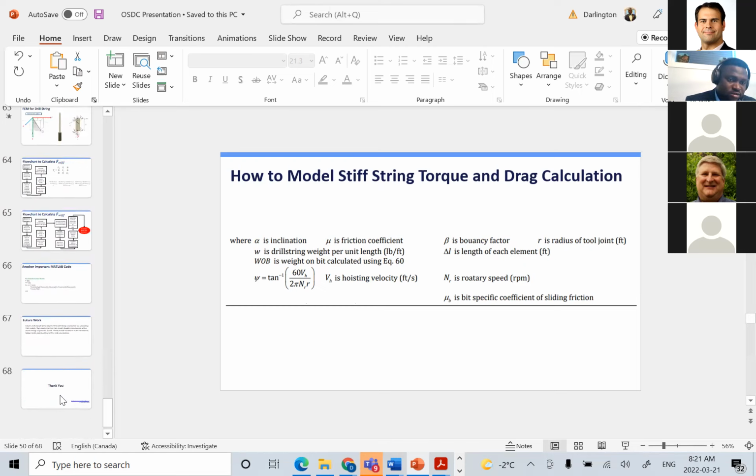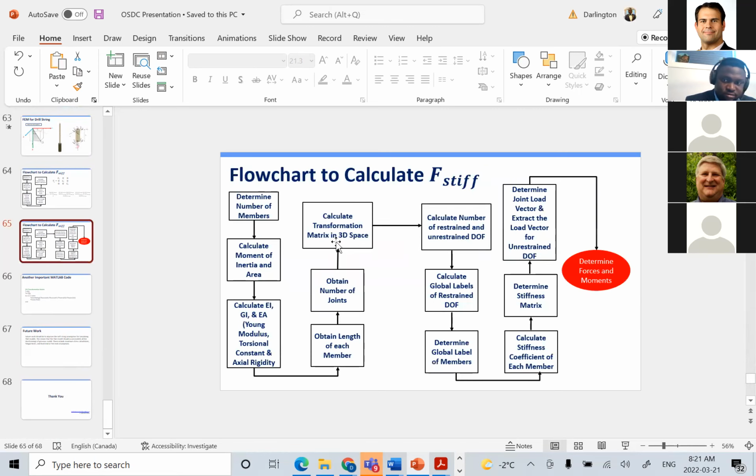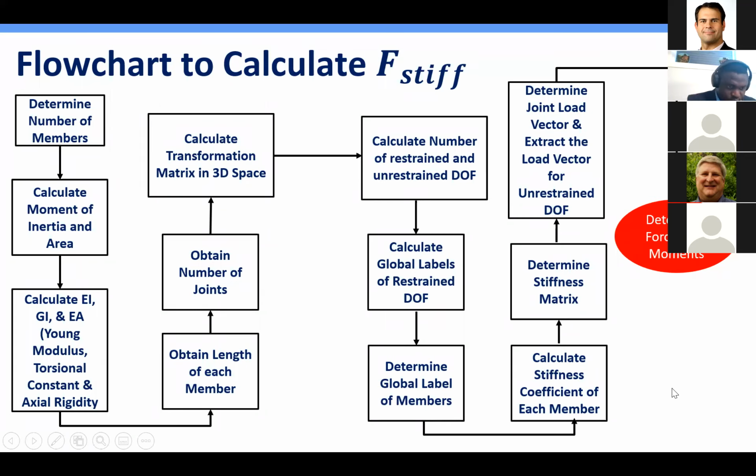Yeah, I can reinforce that as well. Again, in these super long ERD wells that we drill, and actually this has just shown up again in some of our land US wells, which are starting to get pretty long, there is a shear force on the outside that is significant. So if you measure the hook load with pumps, let's say off, or at a low pump rate, and then you bring them up to full pump rate, you can have multi-thousands of pounds difference in hook load.